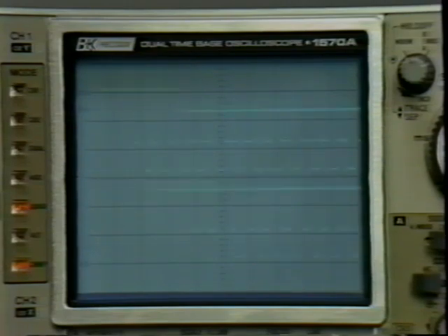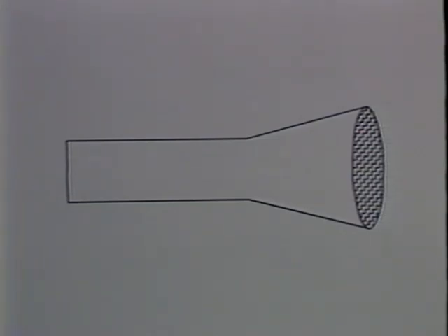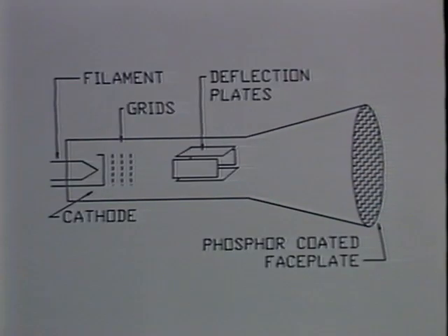Now let's take a look at how the oscilloscope produces its graphic display. The oscilloscope uses a cathode ray tube as its display surface. This is a special purpose phosphor-coated vacuum tube, similar to the picture tube on a television. The face of the CRT glows when a beam of electrons strike it. A pair of electrostatic plates produces magnetic fields that move the beam around the face of the tube. The moving beam striking the phosphor produces the image that we see.